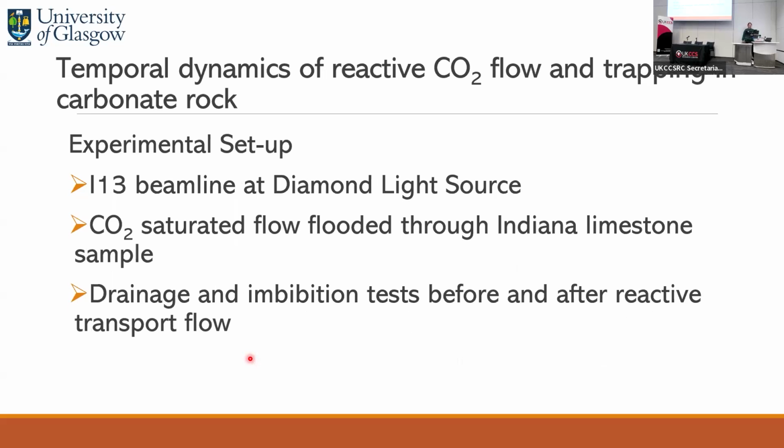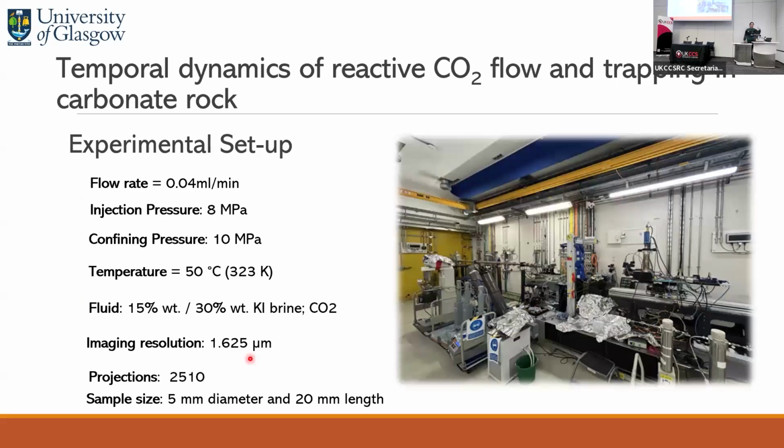We conducted CO2 saturated flow. In the carbonate sample, we conducted drainage and imbibition tests before and after reactive transport. So what do we have? They have a similar setup. We have a very low flow rate, the capillary flow rate. We have injection pressure, confining pressure, 10 megapascal, 50 degrees, assuming 1,000 to 1,500 meter depth, but different flow for different density. We compare the gas phase and fluid phase, right?